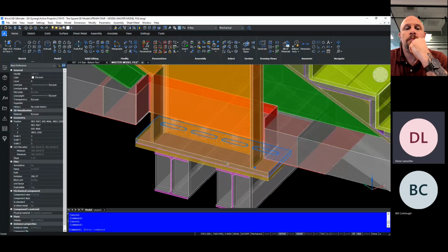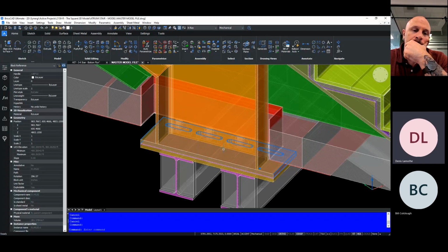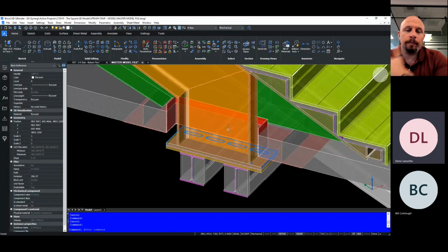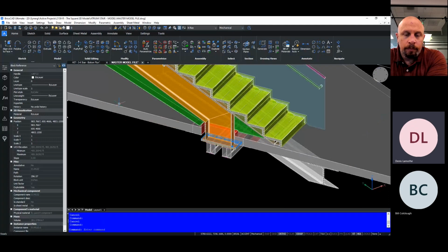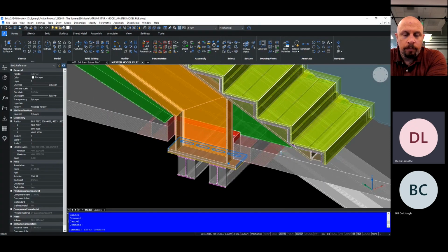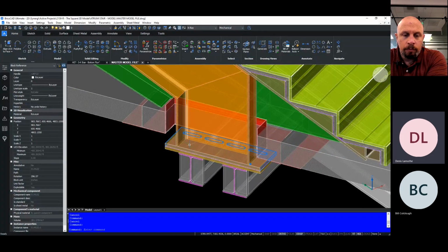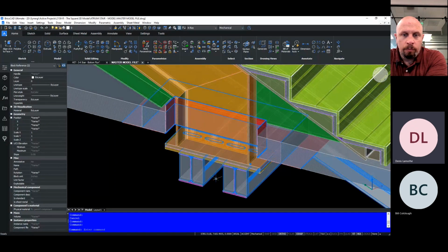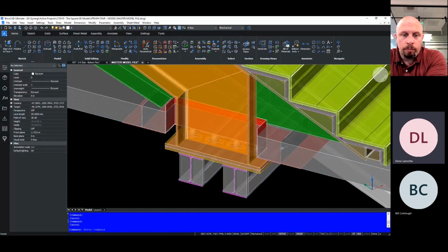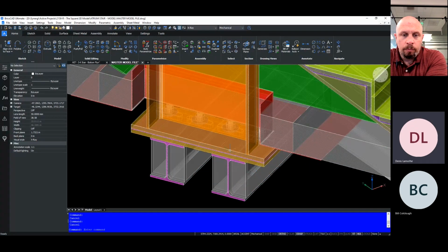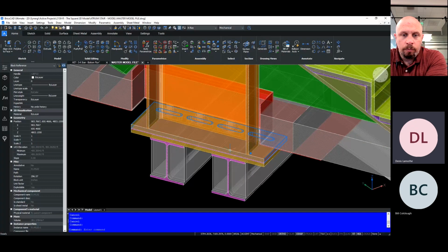We have a portion of a plate section here. When we're attaching the stair at the bottom of the floor, if there's no openings in the floor, we can sit either on top of the concrete slab, or if the slab's not quite designed to hold the weight, the architect may anticipate the need for a cutout in the floor slab, and we can extend our stringers through the opening and have it supported by structural beams below the floor. Either system requires use of a base plate, and I'm sure you know this.